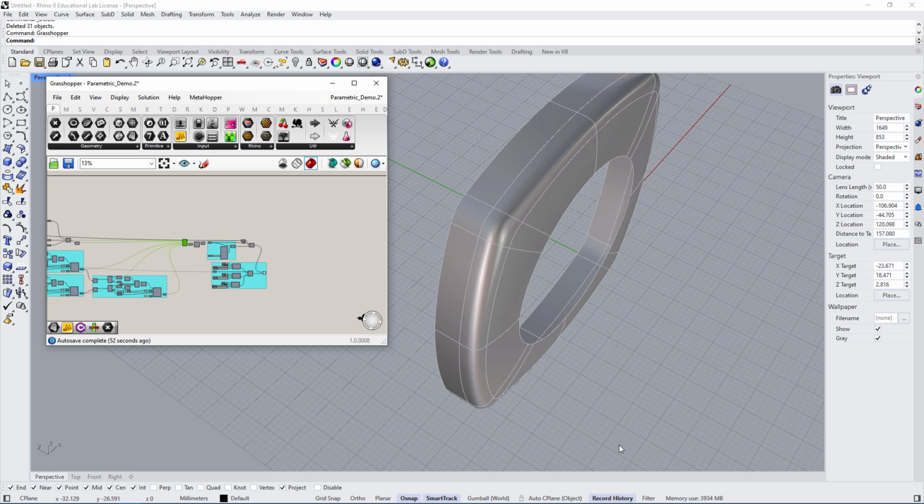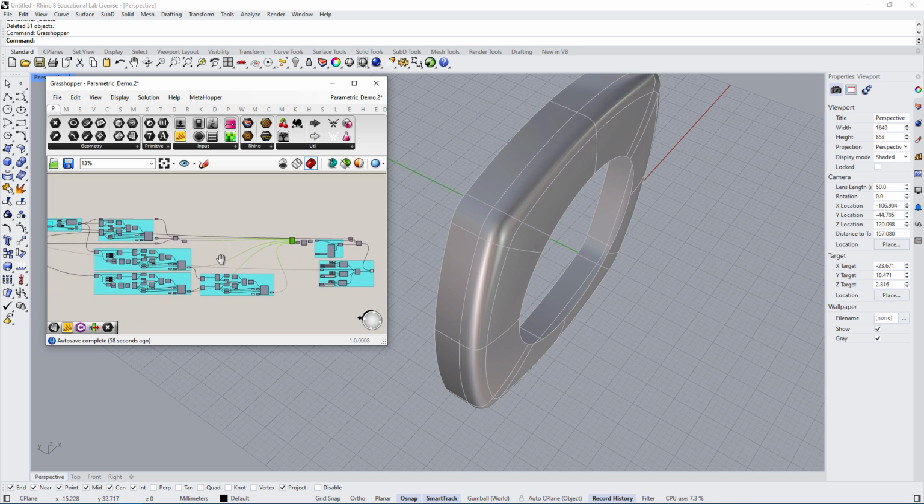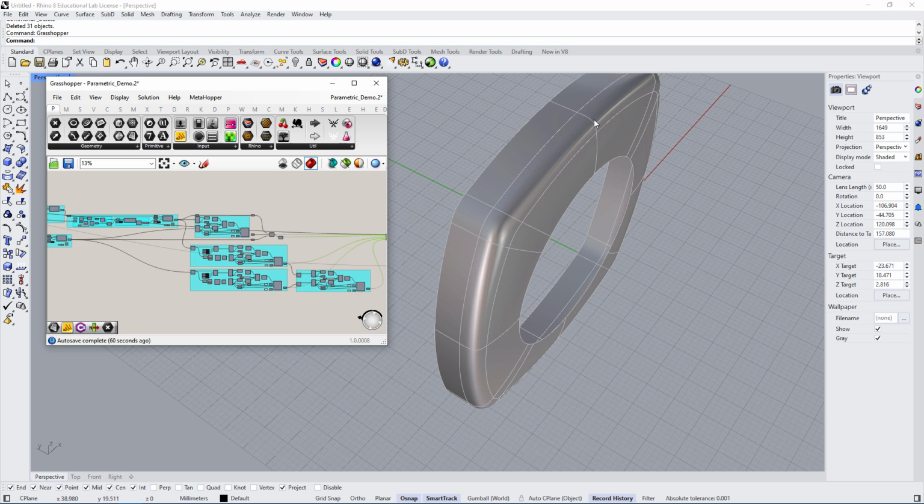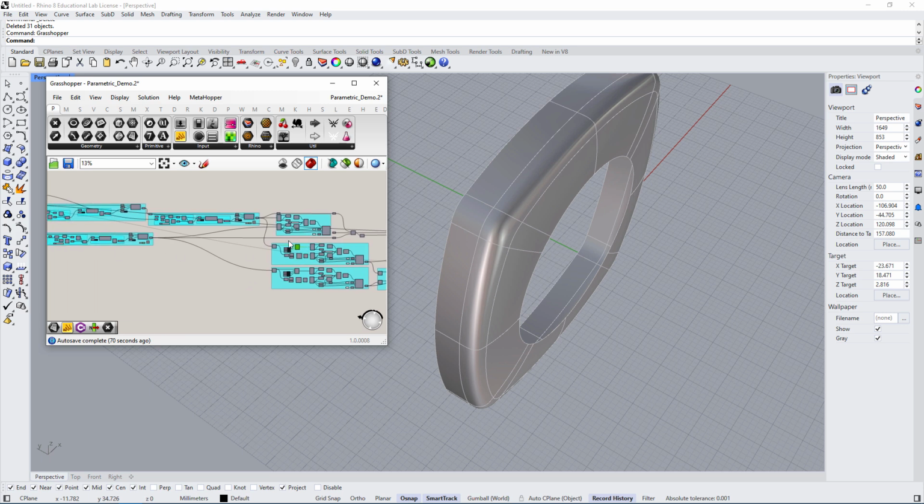And in Rhino, by default, the way you create a transition is you simply select an edge. Now, within a parametric design, you're going to have to define which edge you're using, and you may want to automate the process. So you may have to say, out of the entire surface, look at each of the edges. So now you have two components to say that. You have a surface and a way to look at the edge.